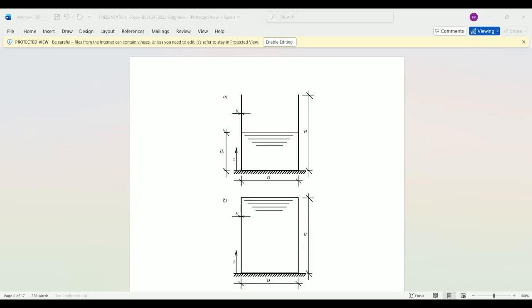The tank under consideration represents a circular cylinder of thin wall. The bottom of the tank is placed on a rigid base. The top of the tank is open. The tank has non-linear viscoelastic behavior. The wall of the tank is functionally graded. The material properties are distributed symmetrically with respect to the mid-surface of the wall.